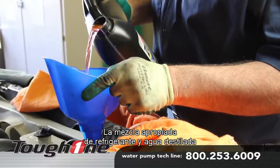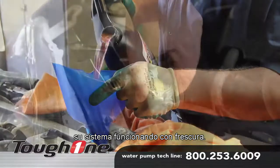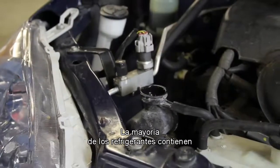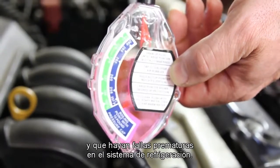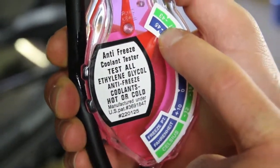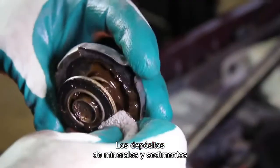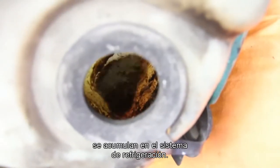Proper mixture of coolant and distilled water are extremely important towards keeping your system running cool. Most coolant contains anti-rust and corrosion inhibitors that prevent sediment buildup and premature cooling system failures. Coolant hydrometers are available at most local parts stores. Mineral deposits and sediments from corroded or malfunctioning parts accumulate in the cooling system.